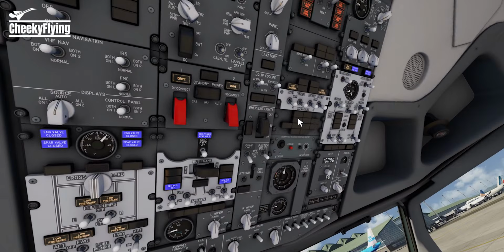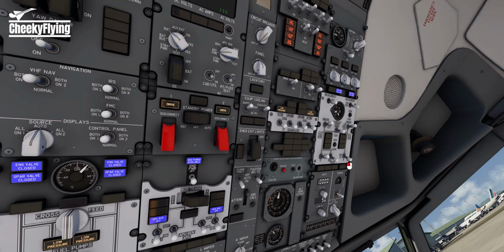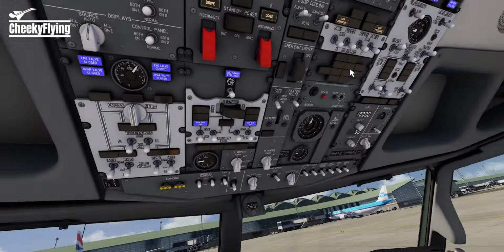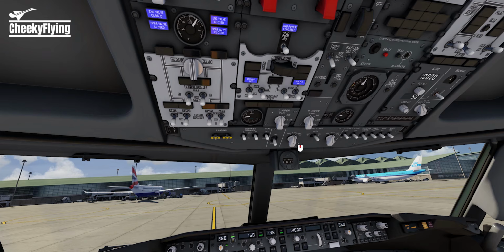To start the engines, we first need to turn off these pack conditioners, these pack things here, and I believe you also need to turn this off. So turn these on as well. And now let us start engine number, is this number 2 or number 1? The left side of the engine first.